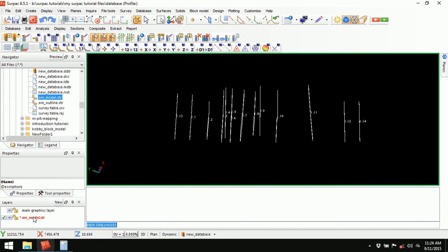Remember, in the layers pane, because we created additional segments 13 and 14, we have edited the original segment. That is why you can see in the layers pane the file name allmodel.string now appearing in a red font, and it has a small asterisk here, meaning that you have not saved it, because if you open an object in graphics, the name of the file appears in the layers pane, and whatever work you perform in the graphics, because you have a mark here, it means that layer is the active layer.